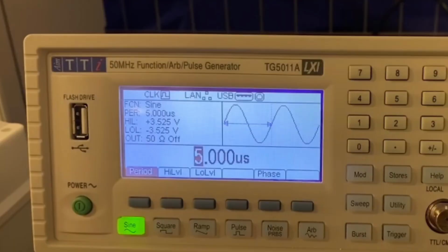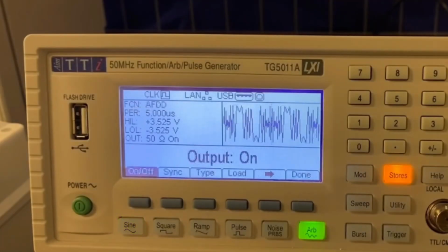Well, it's all down to monitoring the shape of the current waveform that the arc creates while it's occurring. We're used to thinking of a healthy AC supply of current looking something like this, with the current rising and falling predictably and evenly. However, in reality, it's actually a lot messier, even in a relatively healthy circuit, and in a circuit experiencing an arc fault, it's likely to look more like this.